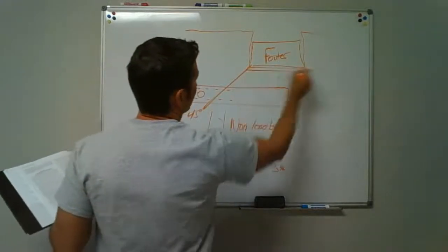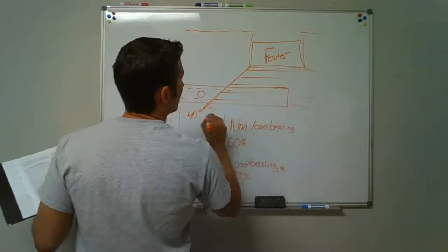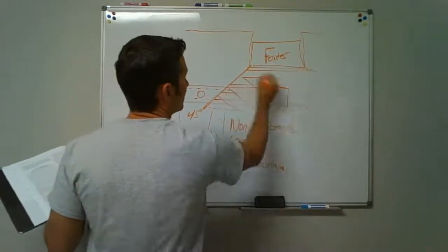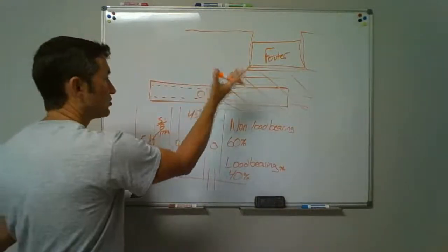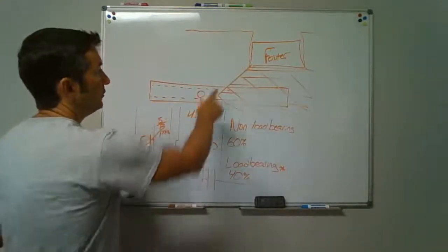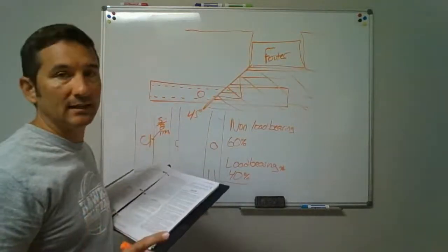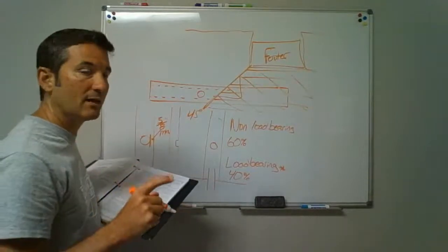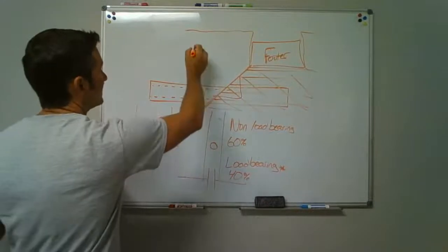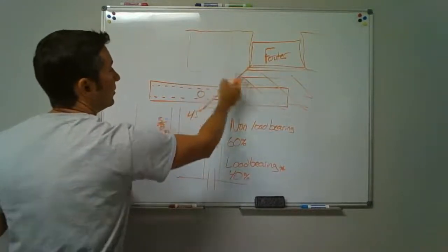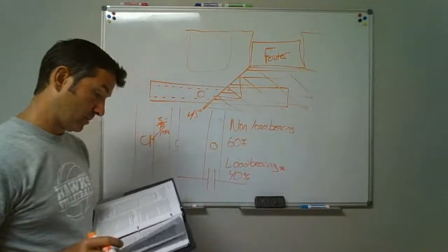We cannot get into this dirt under this hashed area in here, which is providing structural strength for that footer. If you dug down into here, we're now what's called undermining the footing. We're weakening that footing. So come from the corner, 45-degree angle out. We can dig our ditches out into here. We cannot let our ditch come down into that area there. Okay.